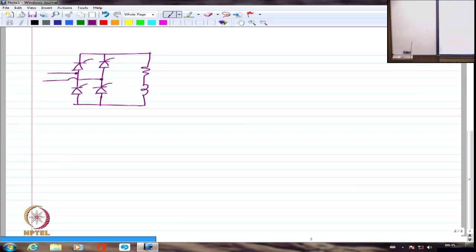We had taken a look with the source that is being connected is a single phase AC source. And most of the times the sources that we consider are generally of 50 or 60 hertz, because these are all power frequency rectifiers, power frequency AC to DC converters, right? So we will normally assume that the frequency of operation is very slow. So the devices will have sufficient time to turn on and turn off. That's the reason why we use thyristors, which are pretty much slow compared to IGBTs or MOSFETs and so on. We are not going to use any of them, right?